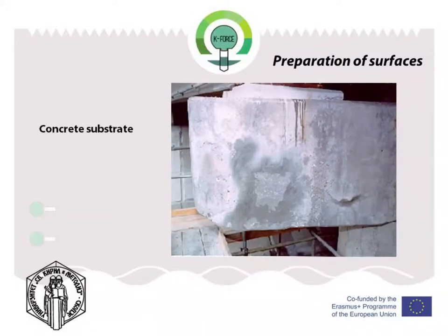Most of the wet layup systems require a smoother surface. Mechanical methods that may compromise the quality of the concrete should not be allowed. Regardless of the method, execution should not damage the concrete. The concrete should be sound and free from serious imperfections like steel corrosion, wide cracks, and potential damage mechanisms. The prepared surface should be dry and dust-free before application of the strengthening technique.